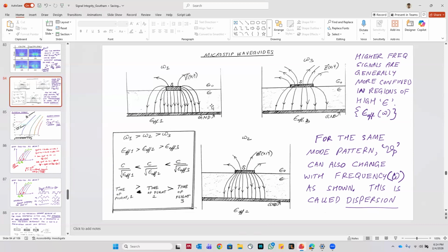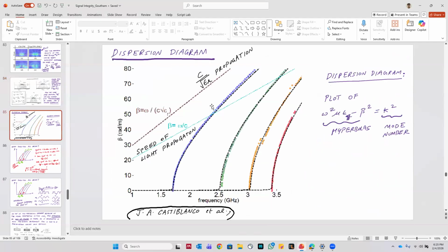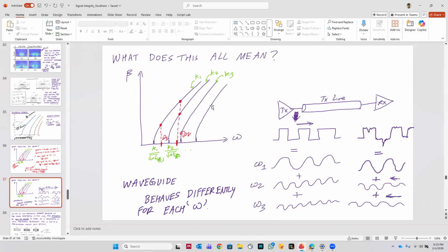And also, if you see most of the high frequency designs, the conductors are usually made very thin because most of the signal is anyway going to propagate at the perimeter. So when you make the conductor very thin, the effective resistance remains almost the same with frequency. It does still decay, but not as much. Okay, so those are some ways you can essentially mitigate this.